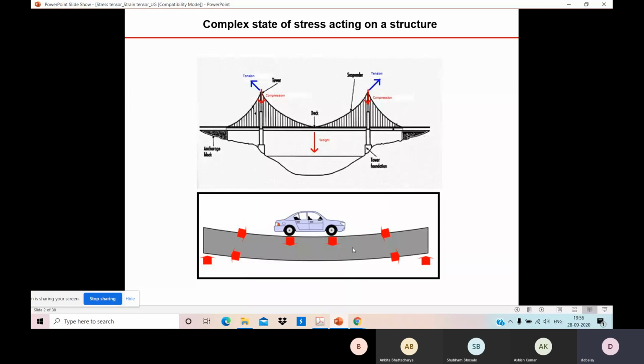And then what we do, we apply a safety factor, and a big safety factor we apply. If I get sigma 1, say 500 MPa, then I will apply a safety factor of 2 or even 3. If I apply a safety factor of 3, it comes down to say 170 MPa.